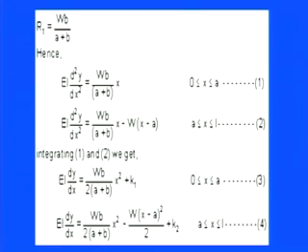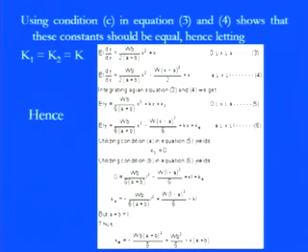So we have the slope EI into dy by dx equal to WB divided by 2 into A plus B into x square plus k1. Here k1 is a constant, and k2 is a different constant for the slope for the BC region. So EI into dy by dx for the BC region is equal to WB by 2 into A plus B into x square minus W into x minus A whole square by 2 plus k2. Now we have the two different constants k1 and k2, and we would like to put the boundary conditions to evaluate the other things.